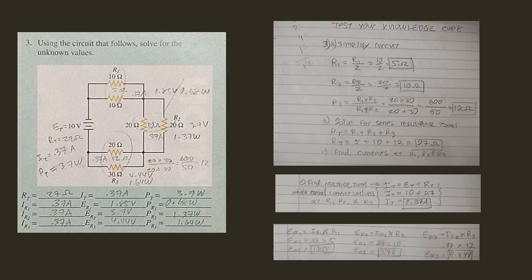The resistances at R1 of this circuit are in parallel. How do we find the resistance of a parallel circuit that has two identical values? We use the division formula: R1 divided by 2, which is 10 ohms divided by 2, or 5 ohms.